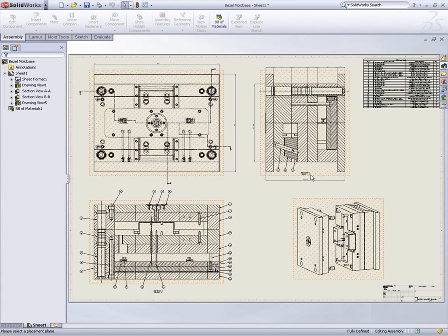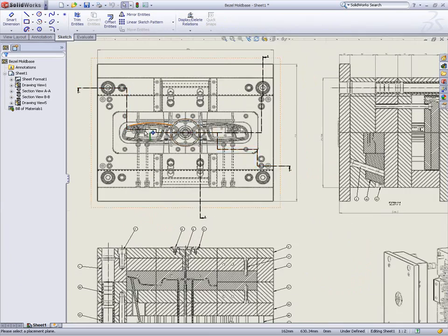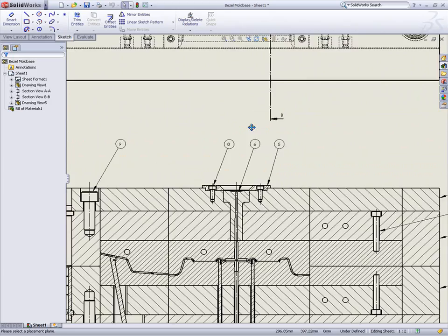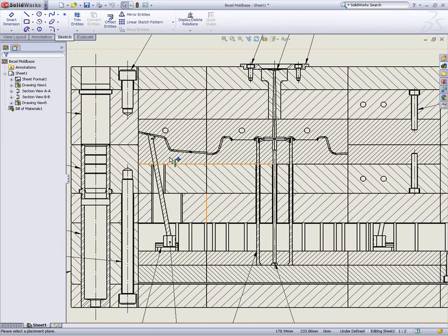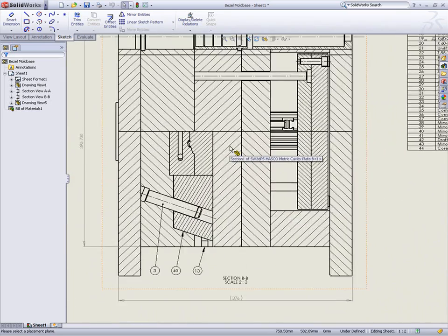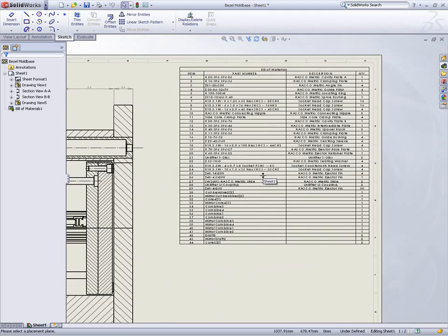No tool design is complete without a full set of drawings. Here we have the GA, which could be used for quotation or for detailing the entire assembly. Typical stepped section views show all the detail we've added. The core and cavity detail with ejector pin locations and waterline features. The lifter. The sprue, runner and subgate. And the side core. And of course, a full bill of materials.